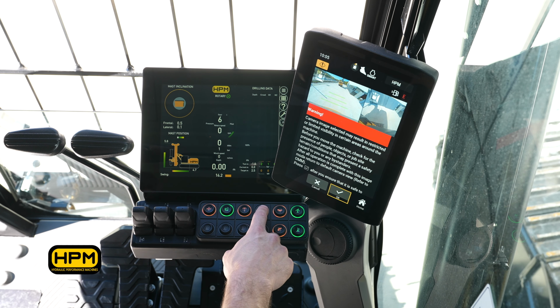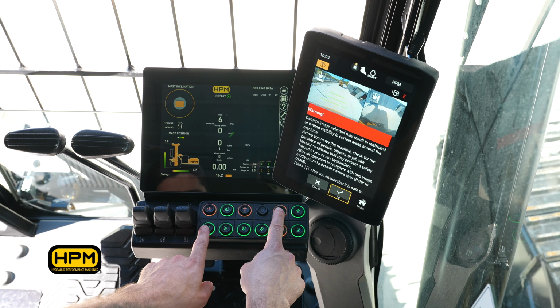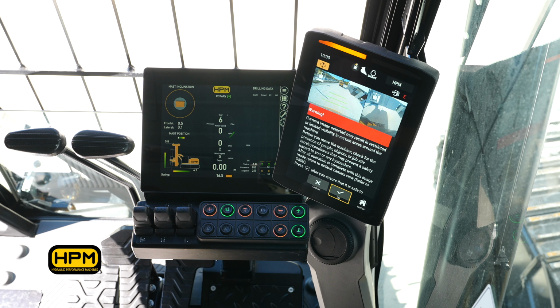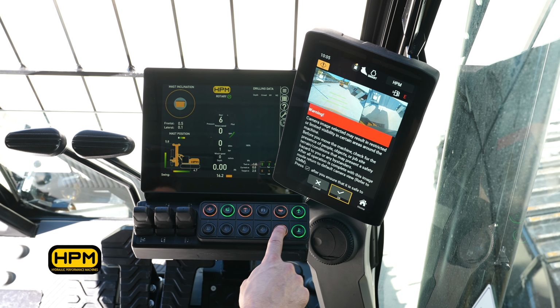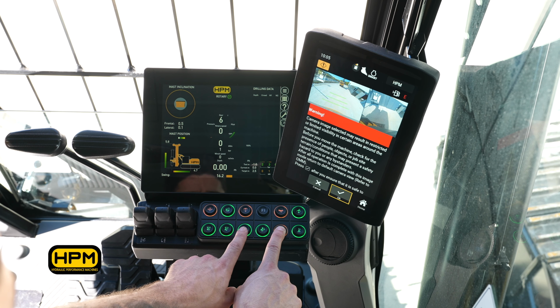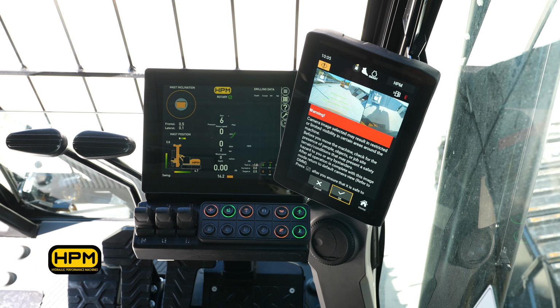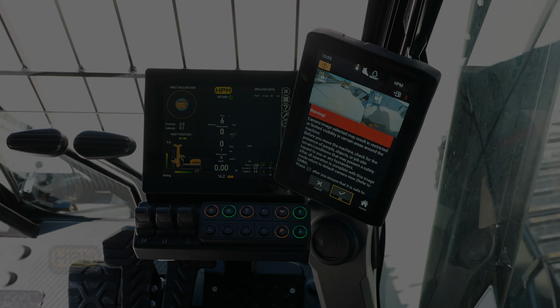Use button 5 to activate 7, 8, 9, 10 buttons for the headmast movements. These are used to open and close the headmast and the auxiliary winch arm on machines where available. Use button 11 to activate 7, 8, 9, 10 buttons for the transport movements. Open and close the rotary and the mast extension on machines where available.